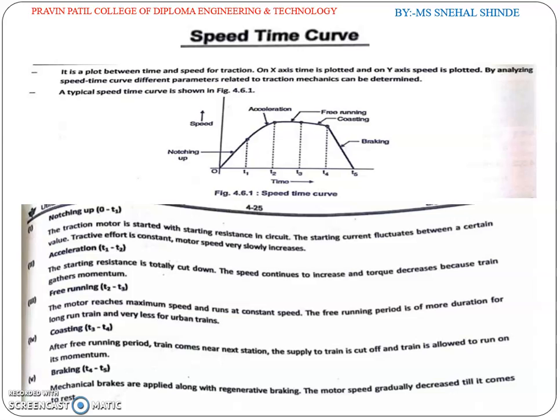Hence, the tractive effort utilized for acceleration decreases. As N increases, the coefficient of adhesion decreases. Therefore, the motor torque utilized to generate tractive effort decreases.